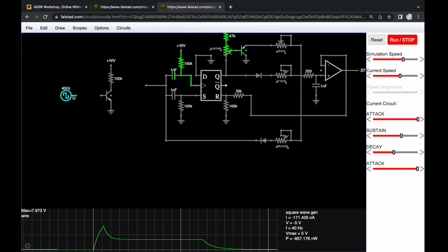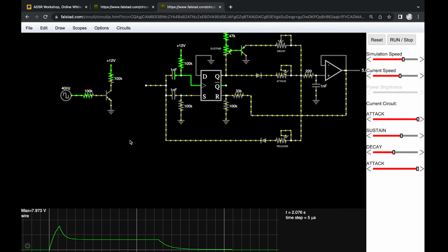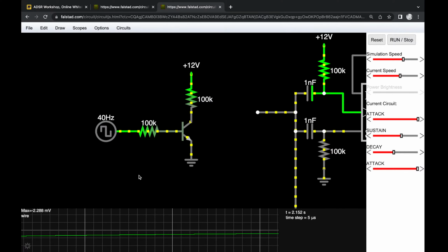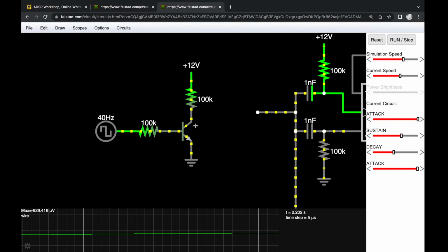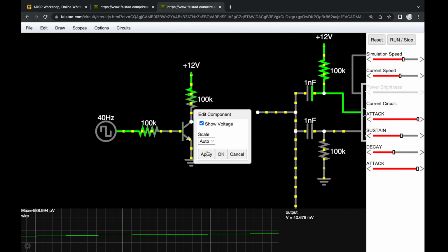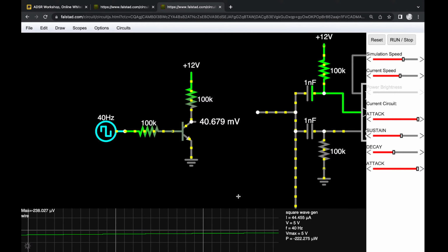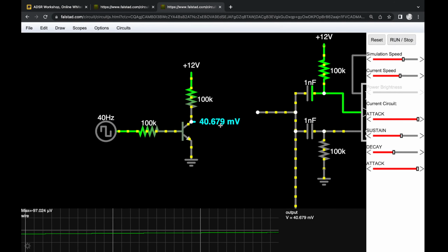And then we will need a resistance over here. A small one, or rather a big one would be better because we don't want to waste current. So we're going to set up a big resistor over here. And if we look at this now, we can see that even though this is just a 5 volt input clock, right? So we have 5 volts here. It's oscillating between plus and minus 5 volts. We get 12 volts and approximately 0 volts over here, right?